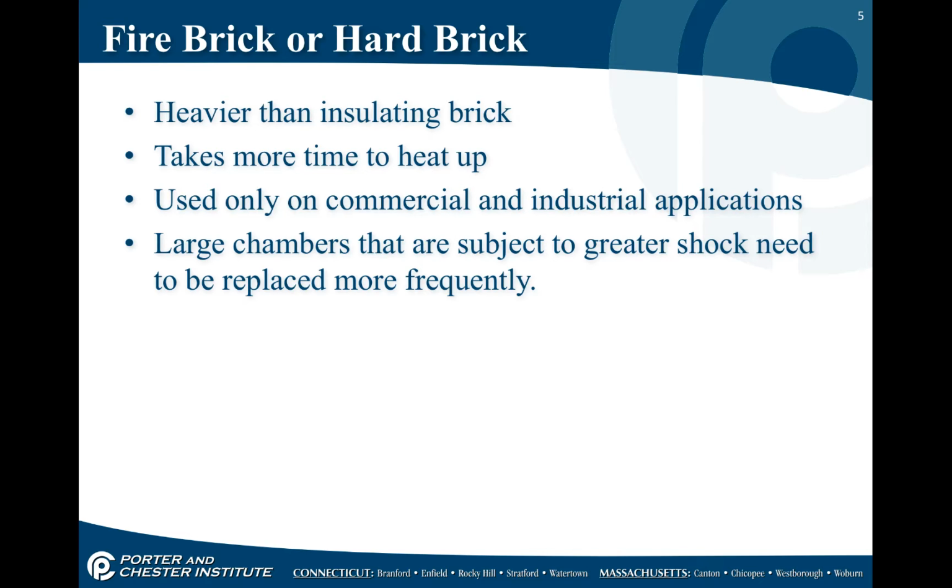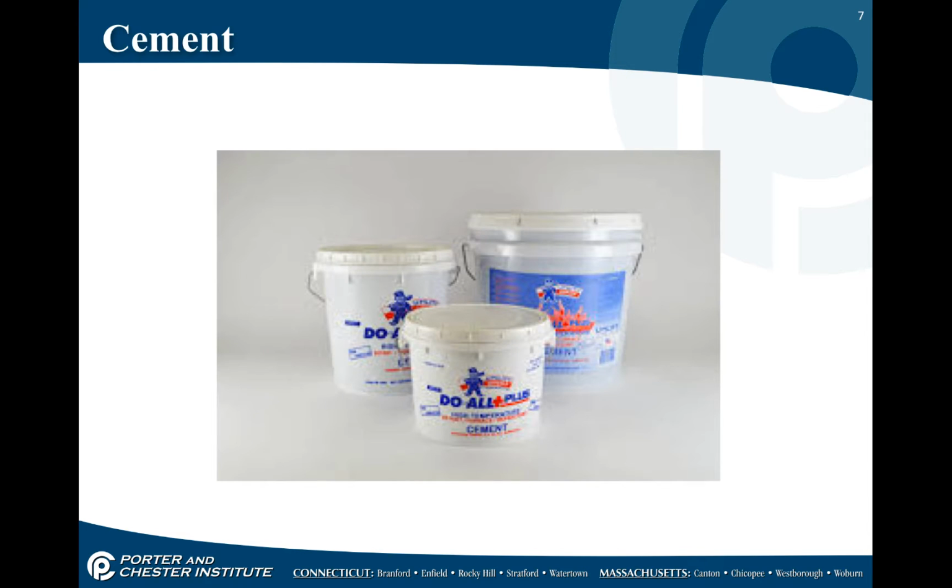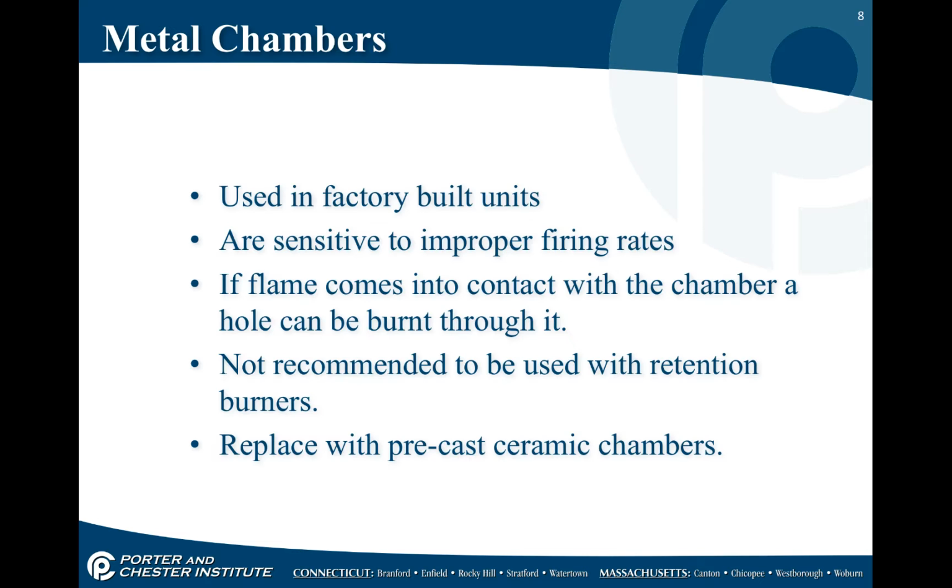And large chambers are subject to shock and need to be replaced more frequently. Remember, as you heat things up and cool them down, they expand and contract. The larger the chamber, the less even this heating and cooling process is going to be. This is an example of the hard brick. And it's all held together with cement. We're going to talk about this a little bit further, but the cement that's used in the brick has to match the brick and the application, or it's going to expand and contract in a different way.